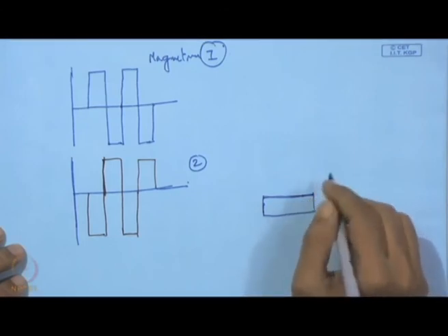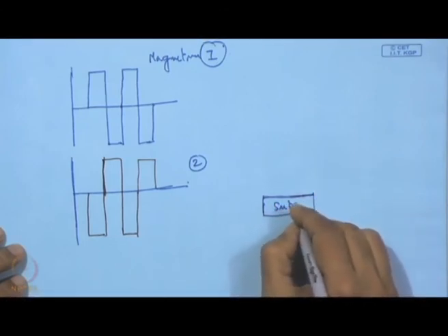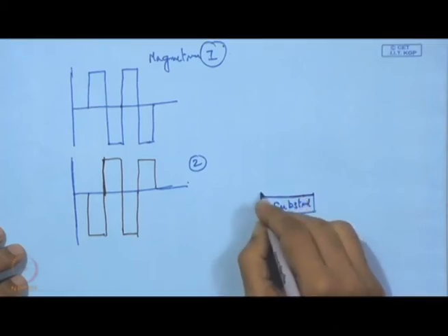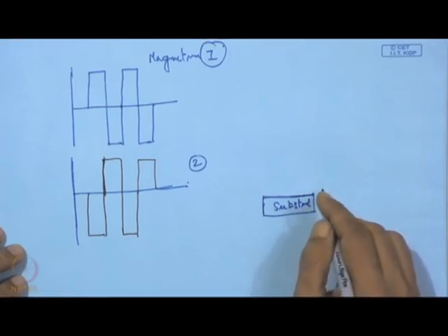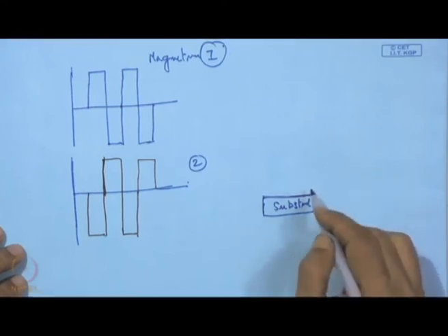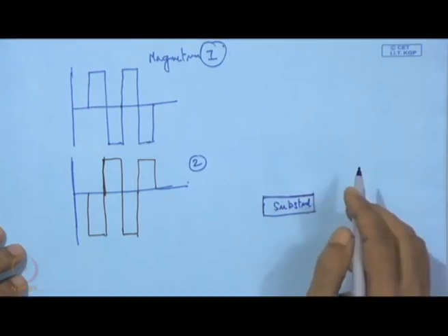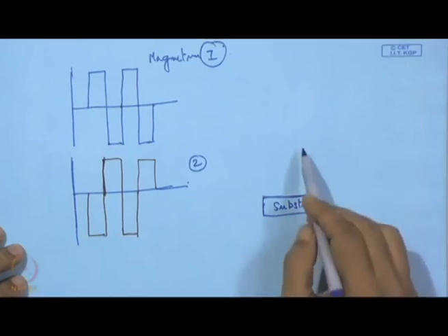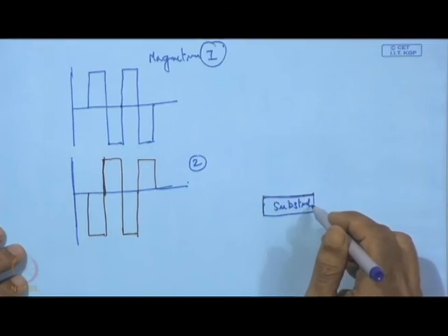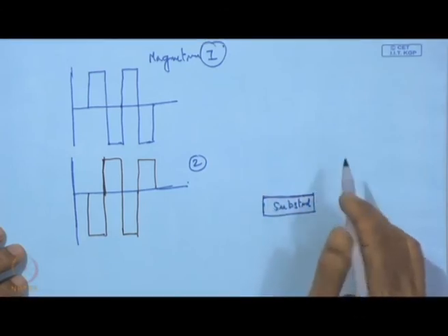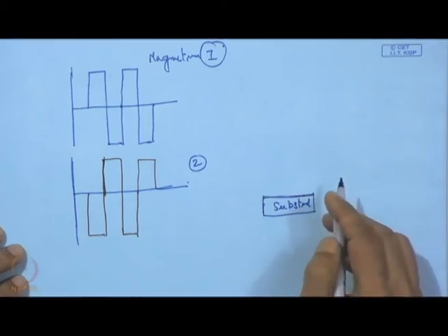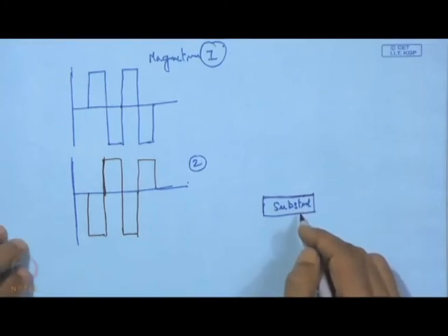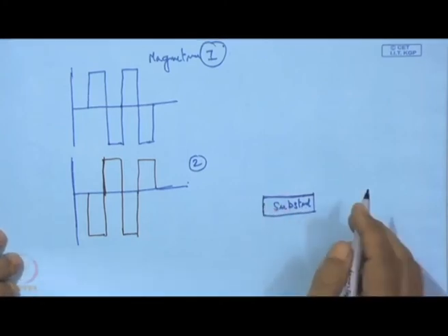For a conducting material substrate, a DC would be sufficient, but when it has a deposited film of non-conducting material, then one needs this RF or this DC pulse supply. So, this is true for RF sputtering also. Once this non-conducting material arrives and covers the whole surface, then it becomes almost like a non-conducting substrate, and proper arrangement has to be made so that we can have such kind of biasing.